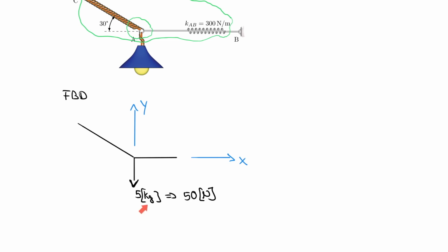And by the way, sometimes I see students solving forces in cable structures in terms of kilograms, but that is not a force. Kilogram is a unit of mass, and if you want to solve for a force, it has to be in force units. So please keep that in mind.